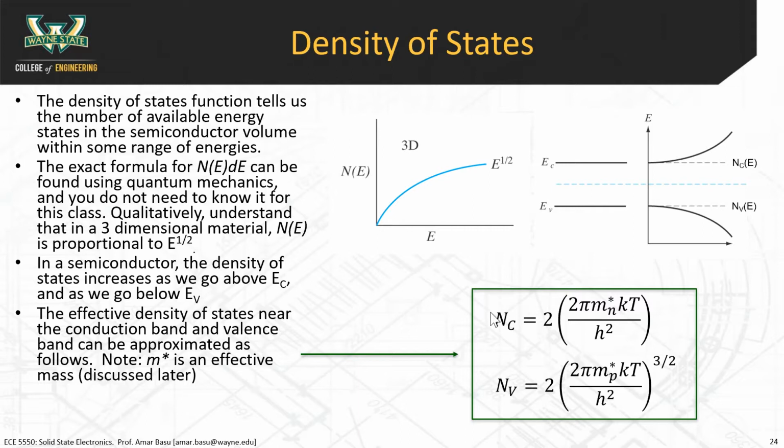If you think about this in terms of the atomic picture, the electrons are residing in those sp3 hybrid orbitals, right? If they're in the valence band, that means they're residing in one of those sp3 hybrid orbitals. If it's in the conduction band, what does it mean? Does anyone remember? When we're talking about these energy band diagrams, an electron in the valence band is bound in a covalent bond. It's in one of those sp3 hybrid orbitals that connects the silicon atoms together.